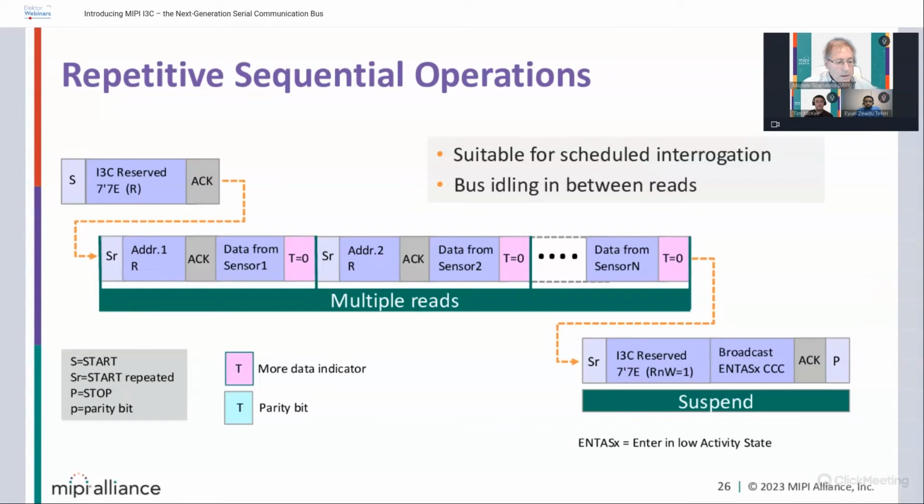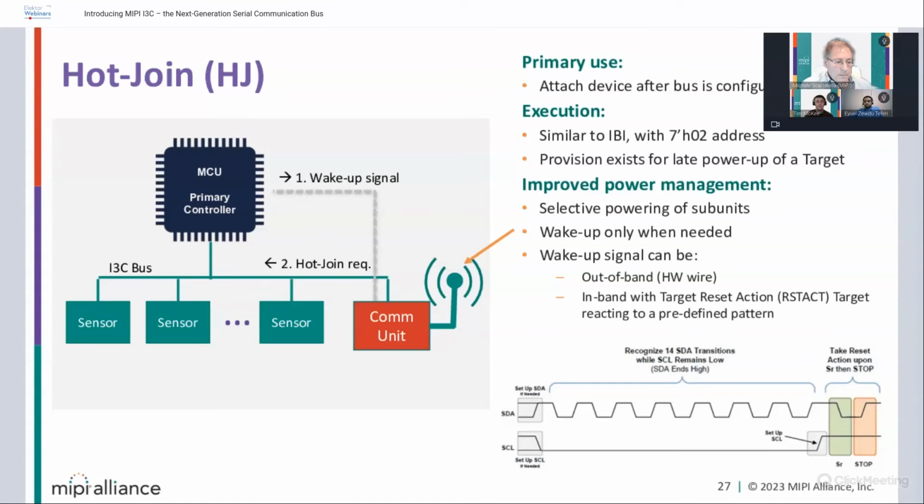Here, by combining a scan, you use the repeated start, you read a bunch of sensors, and then you use a command mode, which is enter bus status low speed. So you wake up, acquire the data, maybe with the asynchronous mode, also with very precise timing information, and go to sleep. For repetitive types of data acquisition, it's very efficient in power and also in computing.